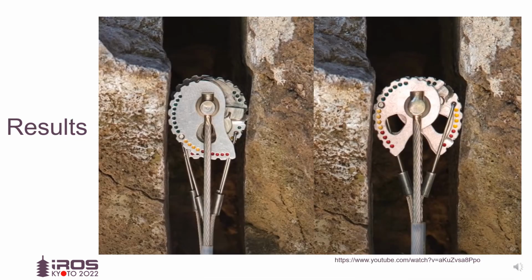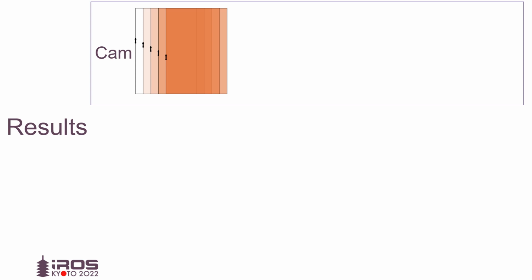Our method can be applied to other design problems and can recover the well-known solution for the design of the rock climbing cam. This cam wedges between opposing rock walls, contacting the walls with constant contact angle, independent of their separation distances. As expected, our solution matches the known analytical solution for this cam shape, a logarithmic spiral.